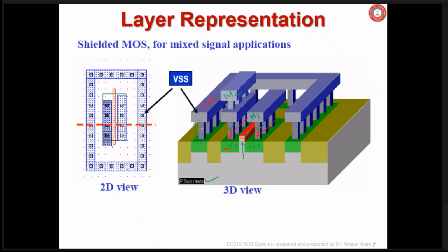Anyway, so while filling, how is it filled? Chemical vapor deposition. This tungsten may be vaporized and its atoms will gradually settle on the holes. Not only holes, every surrounding area will also be filled. A sheet of tungsten will be there. Once it is made, it has to be removed from other places, but this will remain there. The hole will be filled with tungsten.